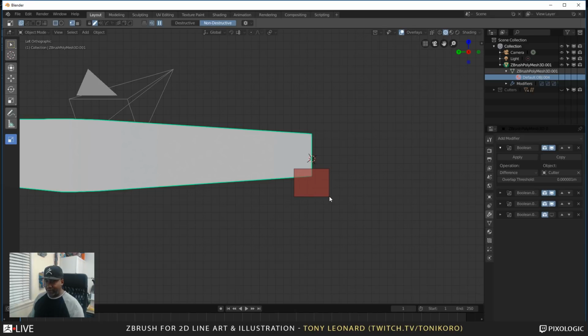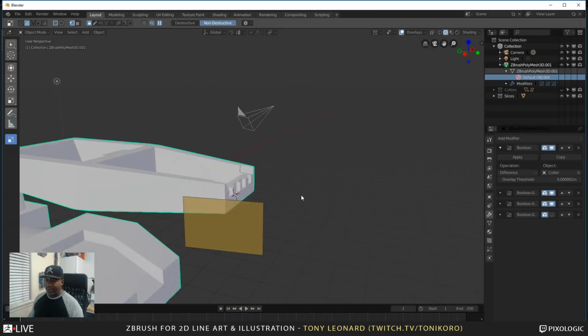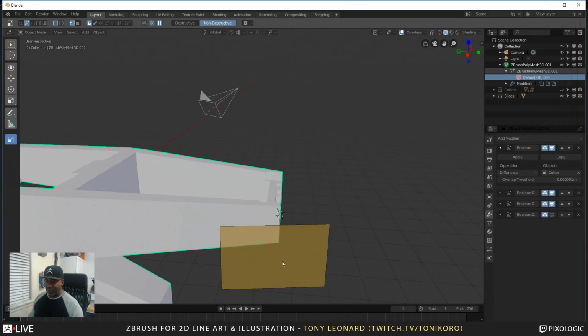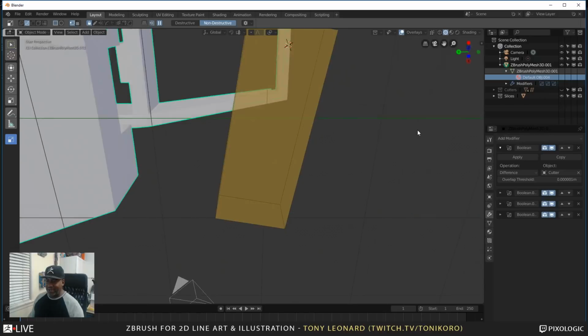And actually this time around, I'm not going to use a box. I'm going to use a yellow box. The yellow box is basically a slice tool. And I'm going to right click it to hold it, and I'm going to hit the space bar to adjust and move it. Right? Because there's no extrusion yet, and this is drawing at the normal, what I'm going to hit is E and expand this out to the other side. This is kind of weird because I drew the box on its normal, but it's not straight. So I need to fix this because it's sitting at an angle.